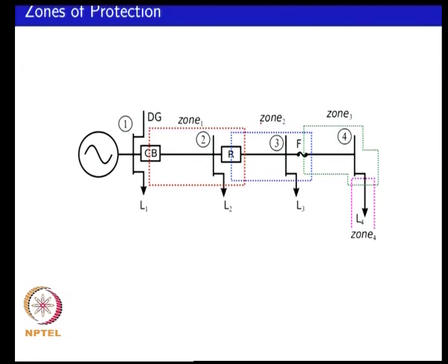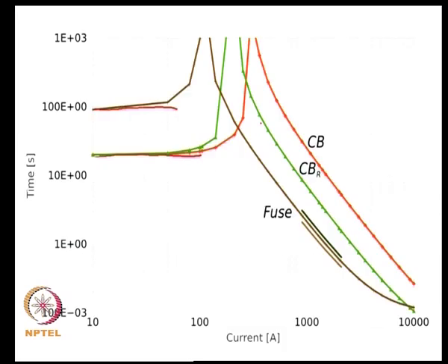So, the next question is to check if the protection systems are coordinated. What you have to do is look at your trip curves corresponding to the maximum or the fault current in the ranges. For example, for CB1 you are looking at 3500 amps to 9.2 kilo amps. So, you might be talking about some current in some range such as this.